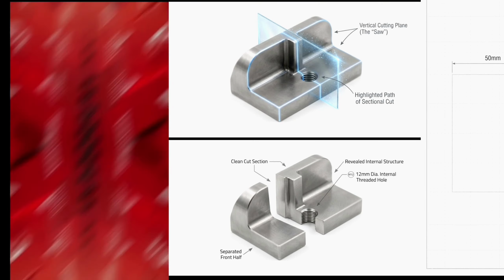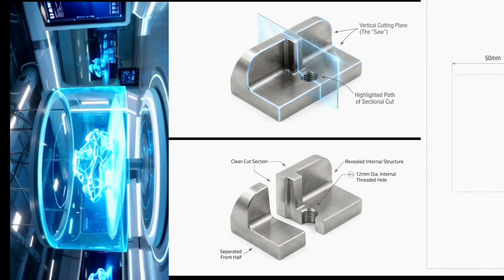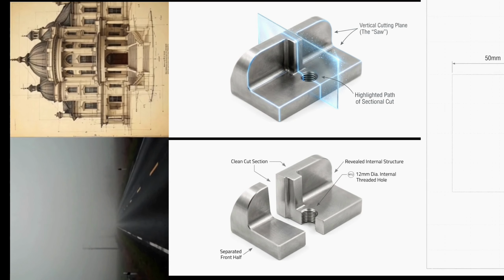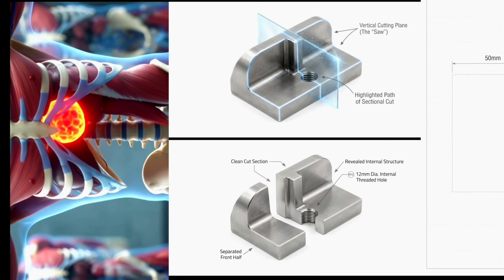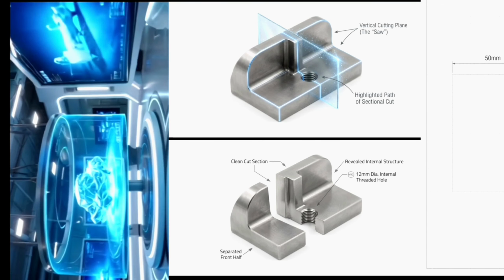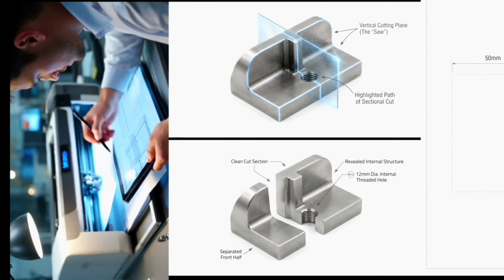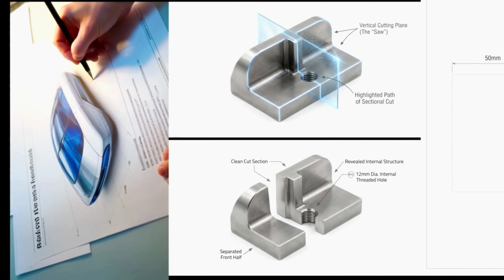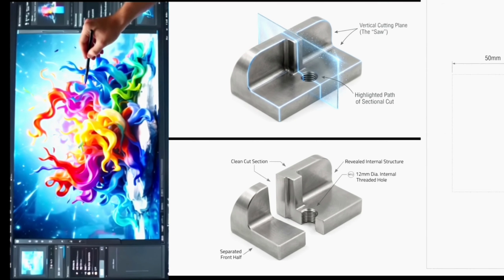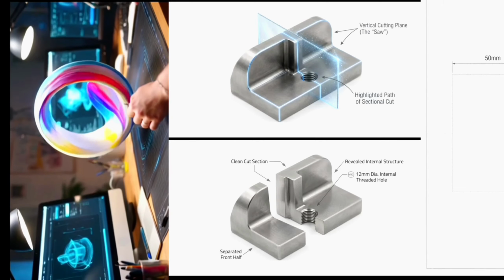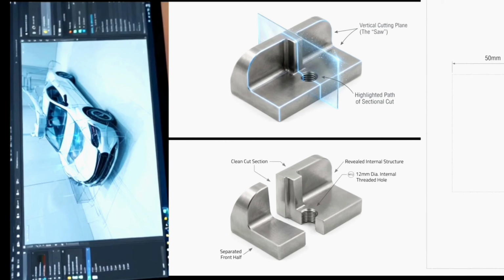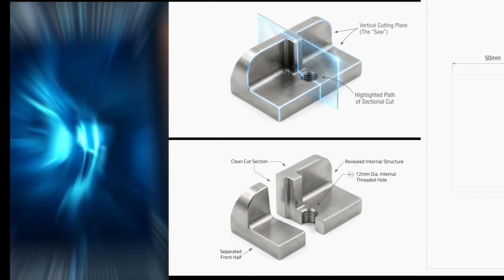Now, let's talk about the sectional view. Imagine a cutting plane slicing through the center of the object. We remove the front half to reveal the internal structure. The base: mark a base thickness of 12 mm and draw a horizontal line. The height: extend the cylindrical section to its full height of 50 mm using your projection lines. The internal hole here is the key, because this is a sectional view. The internal hole is no longer hidden. Draw it with solid object lines. It will appear as a rectangular opening where the cutting plane passed through.